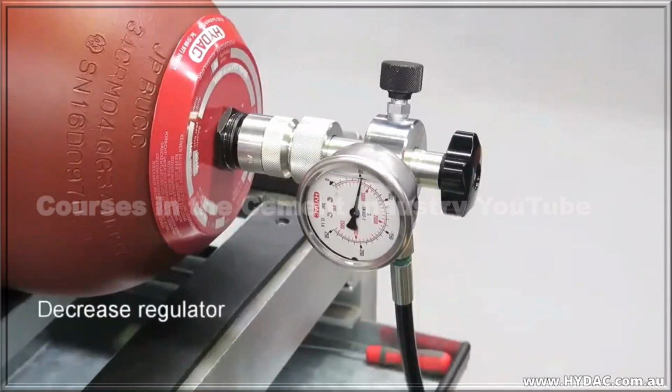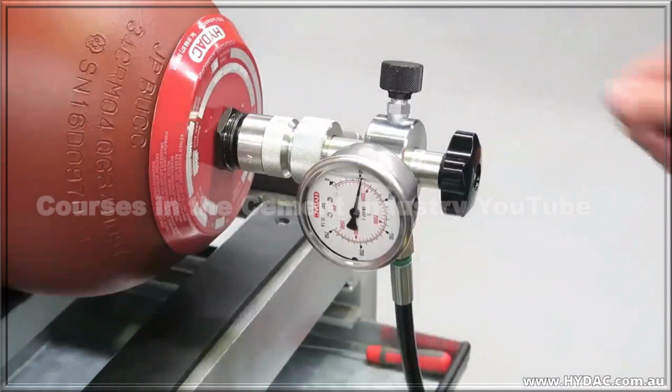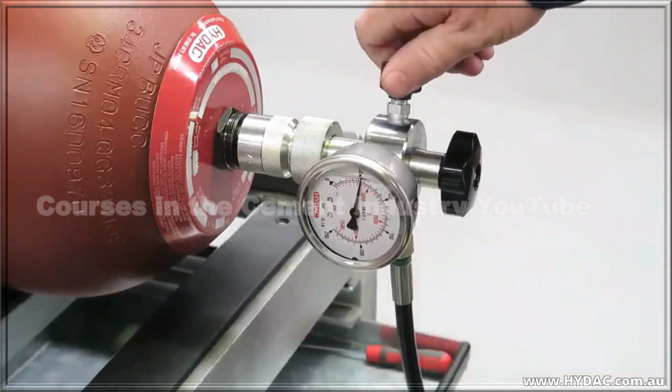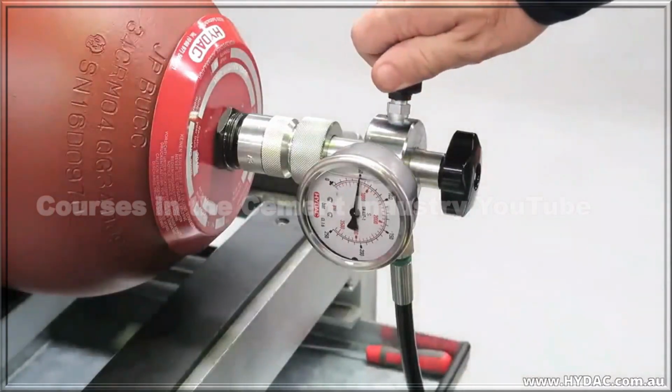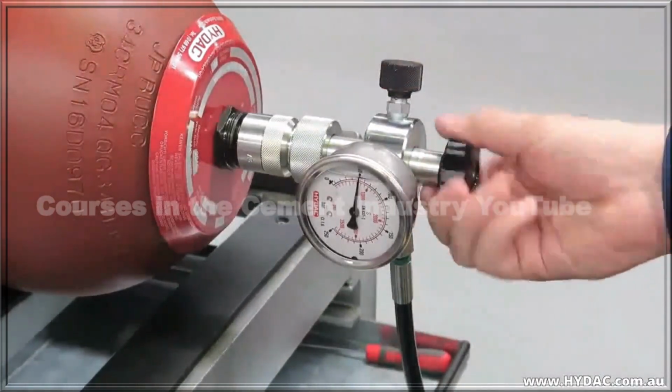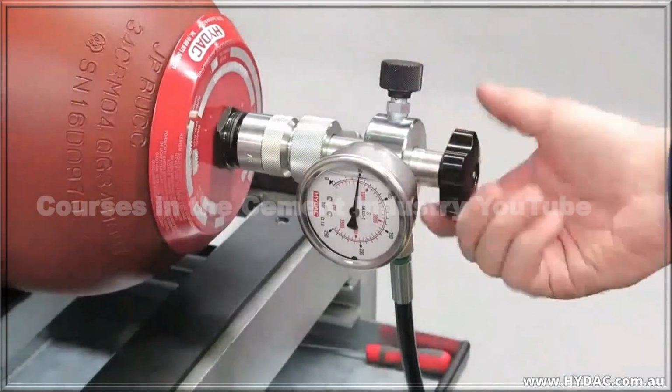Stop the flow of gas by backing off the nitrogen regulator fully. Small pressure changes may occur in the accumulator assembly with temperature changes. It is best practice to charge the vessel to a pressure slightly higher than what is needed. Allow the vessel to cool and then depressurize to the final setting slowly.